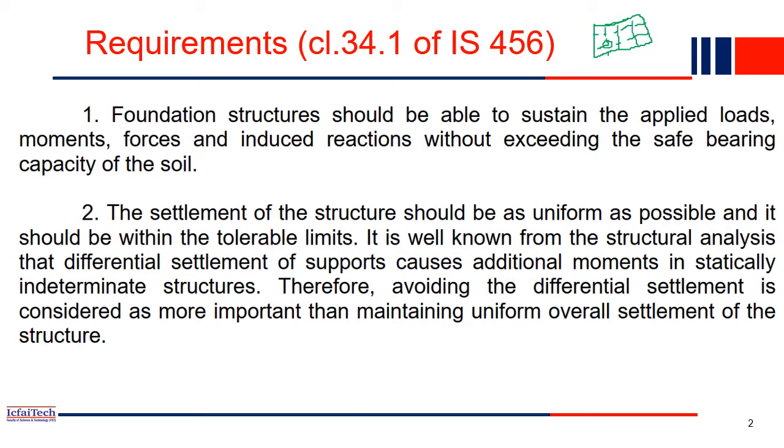So here you have one column, at this point one column, here one column, like that you have multiple columns on a structure, right? So if settlement happens on the soil, we should make sure the settlement is uniform settlement. It means all columns have settled the same quantity or same amount, so that we have to take care.